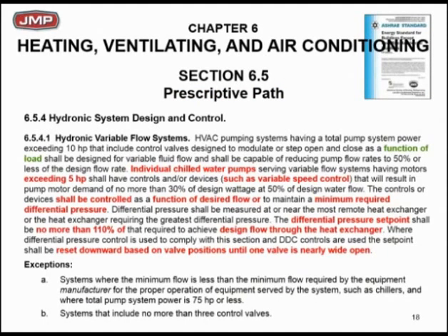Now, why we're talking about all this again is we're basing all of this modern pump selection on the changes. So what is the change? Here's another piece of the code, the standard, and which has become building code. They want you to reduce the horsepower to 30% at 50% flow. They want to vary the flow. A little further down, they want you to change the differential set points on your critical zones to the minimum required to make sure at least one of those valve positions is nearly wide open.